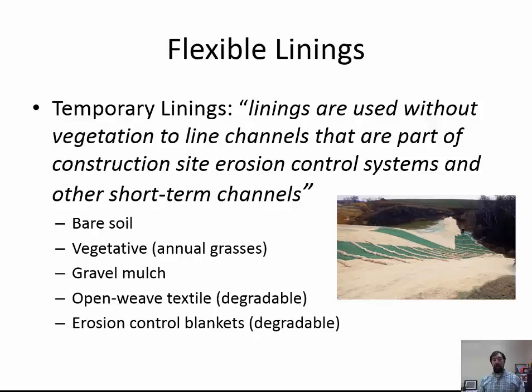Again, think about these linings. They're flexible. They can move with the earth. They could be moved with high flow. They could take some of the form of a stream channel, although most of these are probably used more for threshold type channels. You could use some of these with alluvial channels where we're doing some restoration, and then these things might degrade by the time that alluvial channel is stable. So flexible linings are very different. There's engineering that goes into it, but they're not rigid, and might not require the extensive design that putting in a cast-in-place concrete system might.